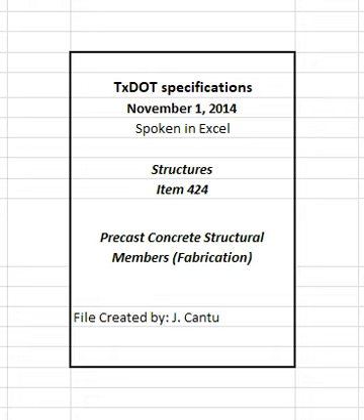4.2.5.1 Placing concrete in cold weather. Maintain concrete temperature between 50 degrees Fahrenheit and 95 degrees Fahrenheit at time of placement as specified in section 424.4.2.5, placing concrete, and maintain the concrete temperature of precast members at or above 50 degrees Fahrenheit during the specified curing period as specified in section 424.4.2.7, curing of concrete. Do not place concrete when the atmospheric temperature in the shade is below 40 degrees Fahrenheit